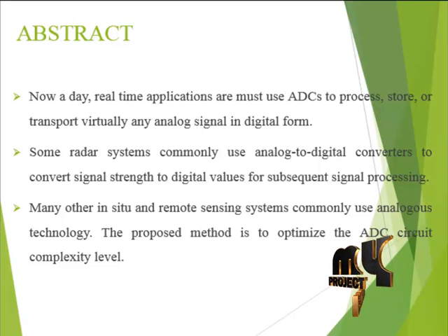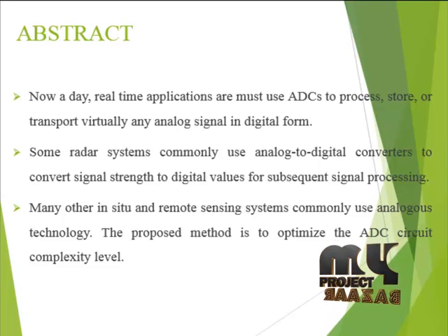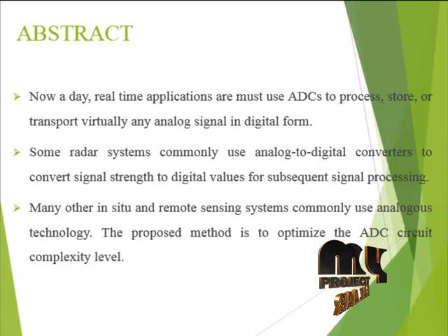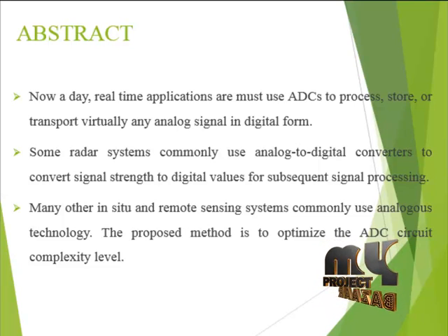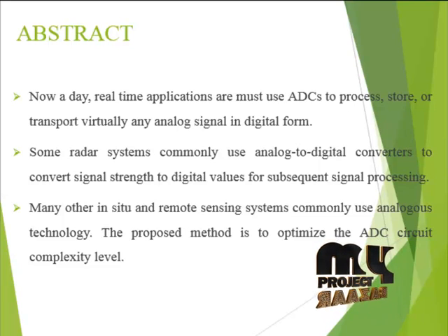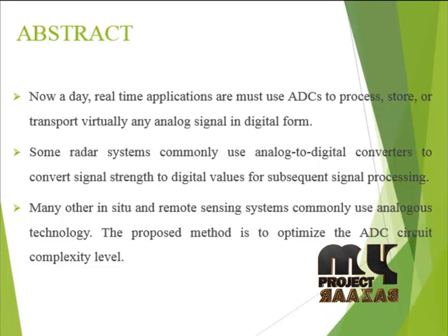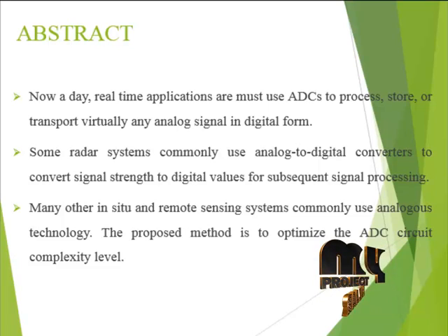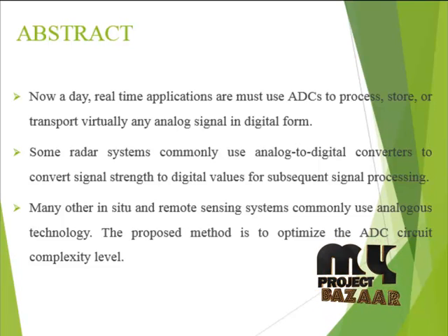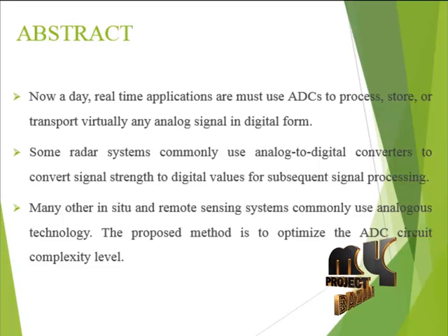Since the pipeline ADC eases the significant loading of the capacitive DAC relative to the noise, it is a good candidate for low voltage and fine resolution applications. Research on the pipeline ADC has mainly focused on the design of operational amplifiers, the op-amp. As CMOS technology scales down, the design of a robust high gain op-amp has become more difficult